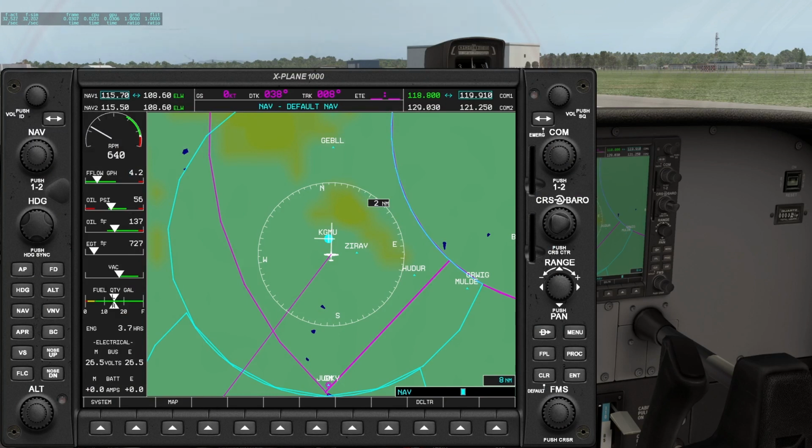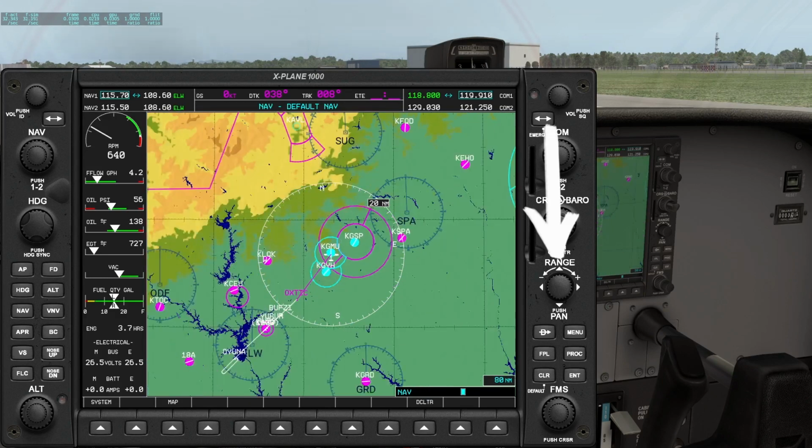On a primary flight display, it shows the same. It can show the same information as this, the multifunction display. It can show the same information as the primary flight display. It shows the moving map, which is really for situational awareness only, and not supposed to be used as direct-to navigation or to stay out of trouble while flying. We can zoom in, zoom out.